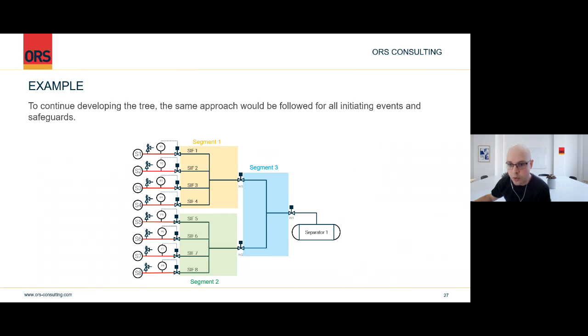Let's see, another one. When we are validating the loop during proof testing, should we do the test like in this tree, for example? Should we need to see that all the SIFs worked at the same time? No, you can perform proof testing for each SIF individually.